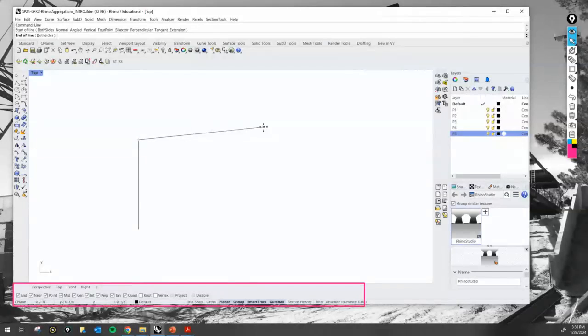And we're drawing a letter size sheet, right? So I'll type this 11 inches, enter. Notice that I'm not done with the command yet. I'm pressing the shift key so that it constrains my cursor, and I have that right there.